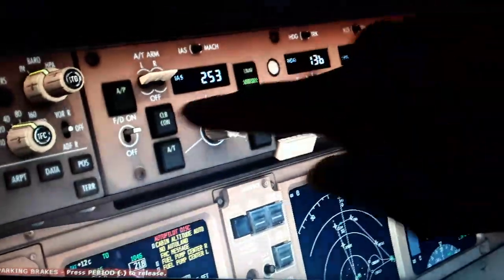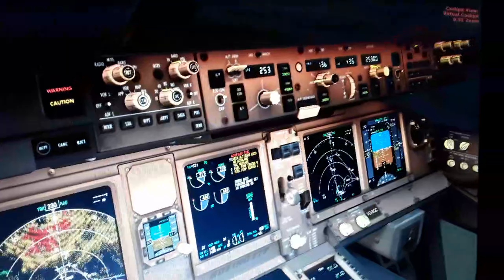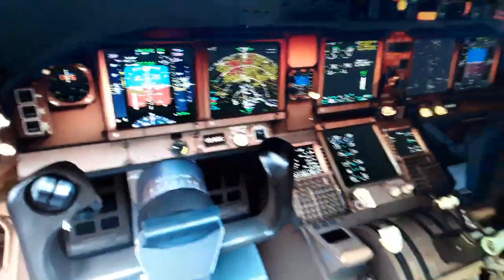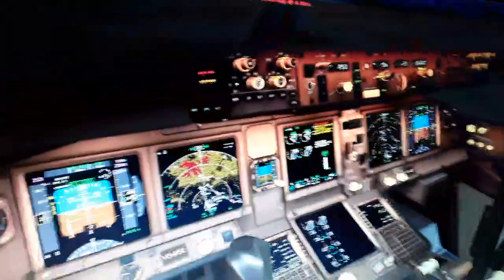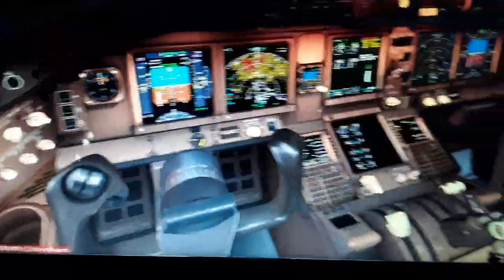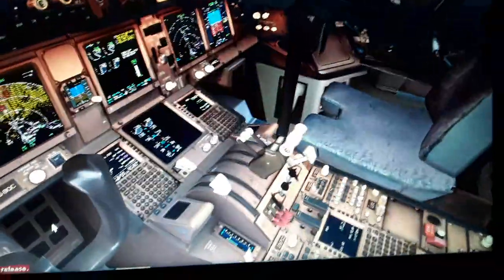So we'll disarm the autopilot now. This disengages the autopilot. As you can see, we have the warning and the red color here, autopilot disconnected. We reset one more time just to see green light on, and we have also this switch here, disconnects the autopilot here. Press one time, we have the warning again, autopilot disconnect with red color, and we press one more time and we confirm the autopilot disconnect to cancel the warning. So this is all we need right now.